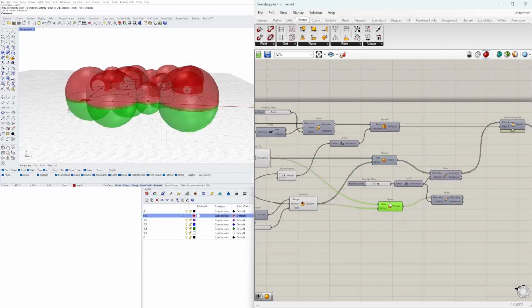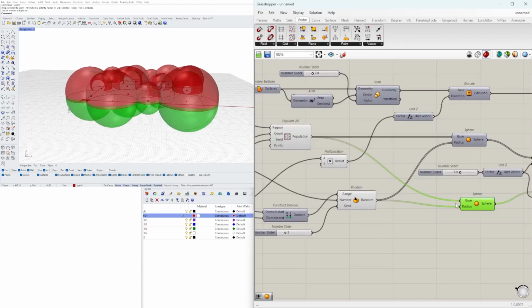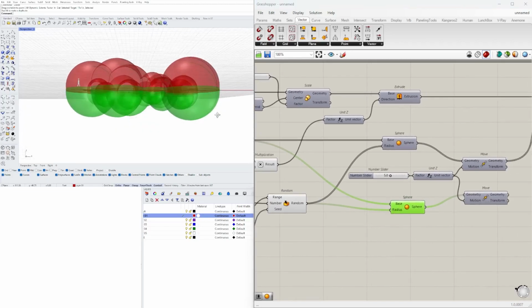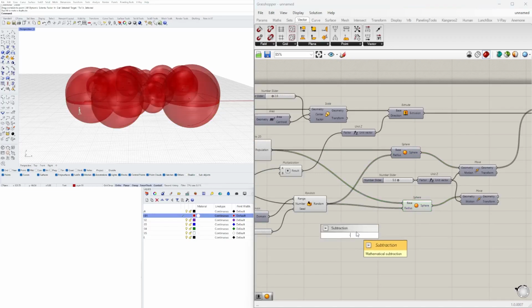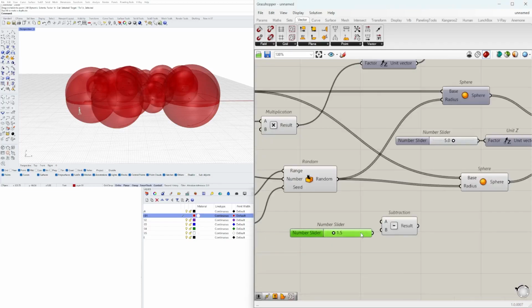Because now all of these random numbers are going into the radius. So what's happening is the radius is actually the same for both of these. We need this radius to be smaller. So all we need to do is subtract the size of the wall, minus 1.5 or 1.5 feet. So we'll go random points come in. The first value is 25. Well, now the output, the first one is 23.8.